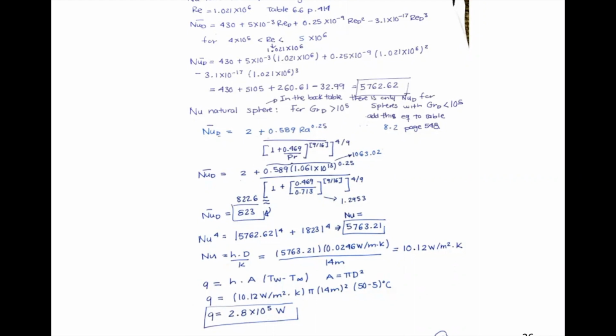So as you can see in this problem, I was already required to use both natural and forced convection. However, when you are unsure if natural convection plays a role, you need to check either your graph in the textbook or do the ratio Reynolds-Grashof, right, to determine if it is necessary to include the natural convection effect or not.